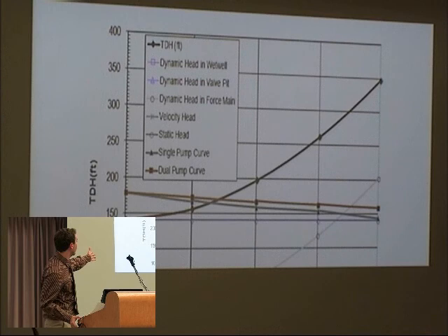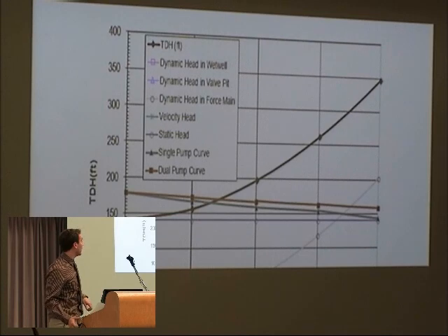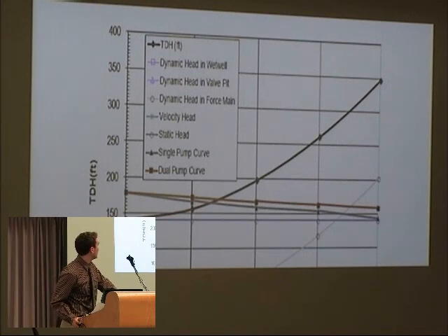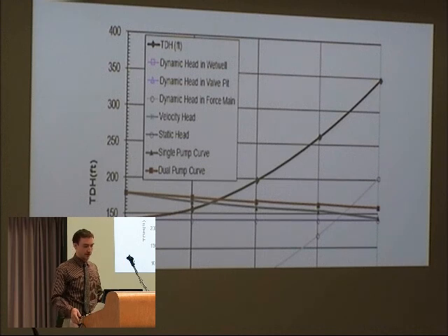This is the system curve I developed based on the factory manufacturer's pump curve and our total dynamic head. The operating point is going to be where the black line meets the blue line, and for parallel pumps, since it's an auto coupling system, there's going to be 2 pumps, and if they are in parallel, the operating point would be at about 26 gallons per minute.